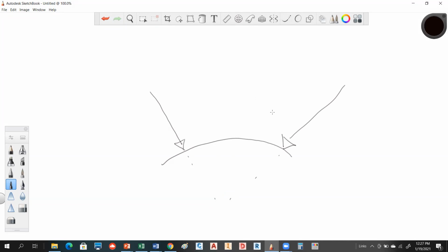If you're doing this in, like, say, a large building, or maybe even on a 2-acre site, for all intent and purpose, they are parallel. So the amount of deflection between these two is negligible. So most of the time, we act as if this doesn't really happen. But if you're dealing with very, very large surveys that we call geodetic surveys, because this distance is so great from here to here on the plumb bob, this deflection and what they call the verticals is very, very important.